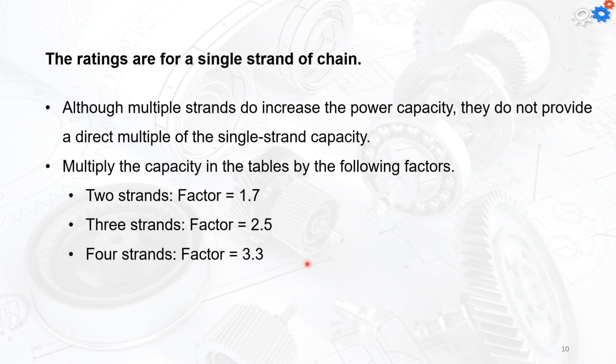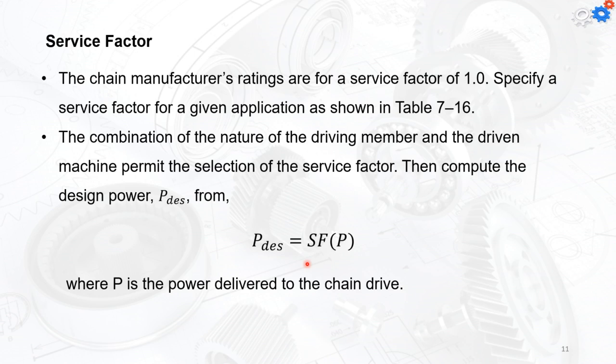So again, the service factor is applied in the design procedure, where we design for the design power, which is the actual power multiplied by the service factor. We learned about that in all the other applications we had, like the gears and the belts as well.